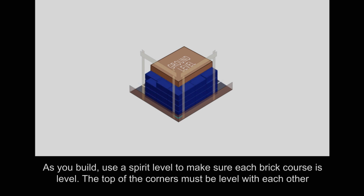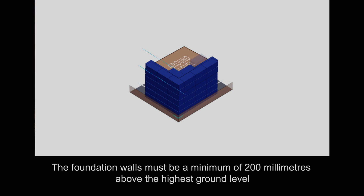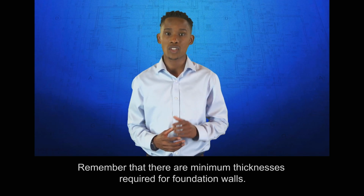Build up the foundation wall starting at the corners. As you build, use a spirit level to make sure each brick course is level. The top of the corners must be level with each other. After you have built the corner, build the walls. The foundation walls must be a minimum of 200 millimeters above the highest ground level. Remember that there are minimum thicknesses required for foundation walls.